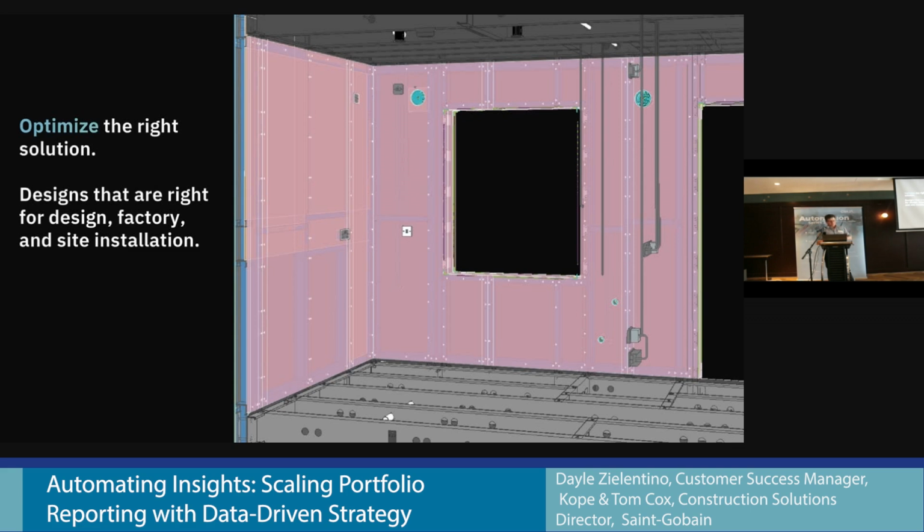And we can get into this process where suddenly we can actually foresee those issues coming through. We can see you've got a wire weight here, you've got pattressing here. The panels are going to work. The panels aren't too heavy for a team to install. The stillages where these panels come together, they can actually be lifted by the crane, and the load locations can work. So suddenly this granular level of detail, informed by manufacturing and construction, can help the design teams actually deliver a better and faster project.